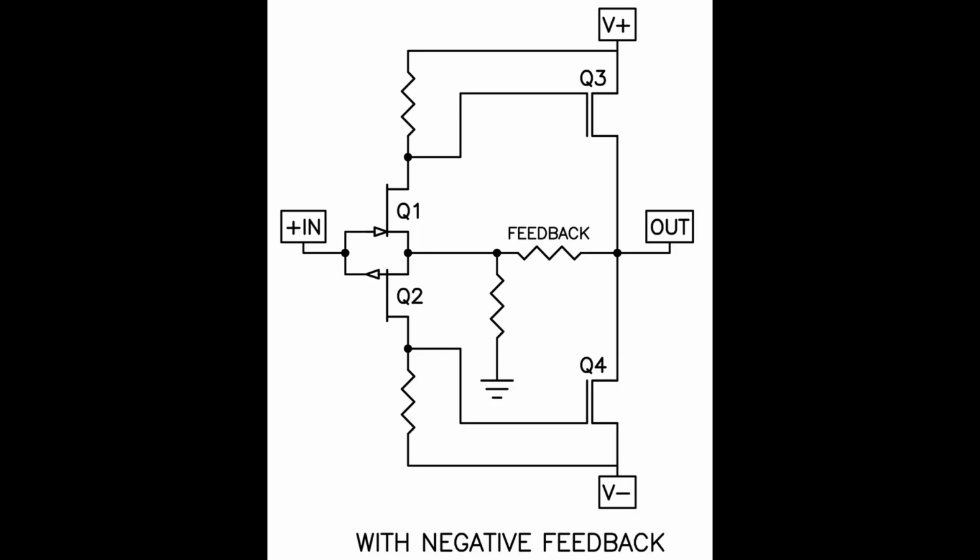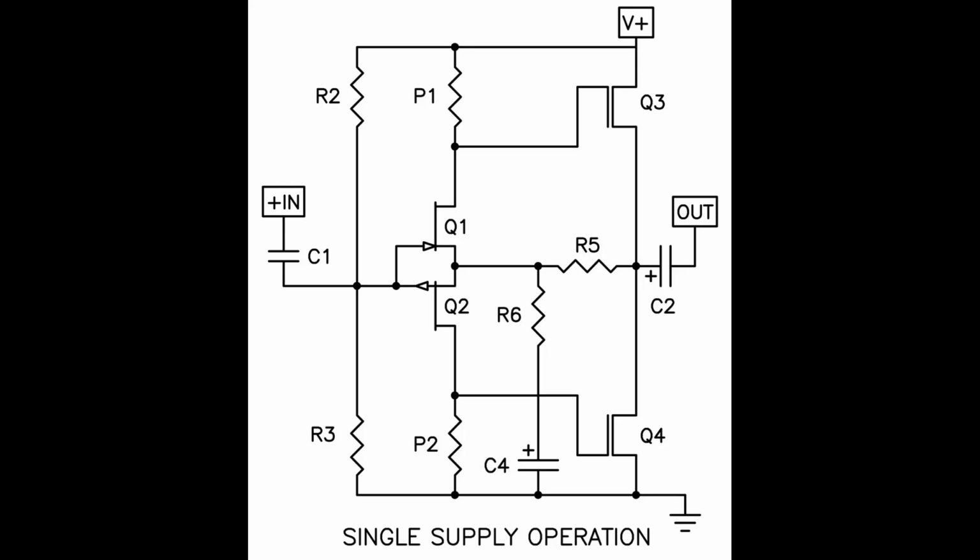The circuit now has lots of gain, more than we can use directly, but we will take the excess and use it to improve the performance. Here you see the introduction of a pair of resistors which feed some of the output signal back to the input in a way that lowers the output gain but makes it more like a large version of the original input signal. Here we add some more details, including some part numbers that will be referenced later.